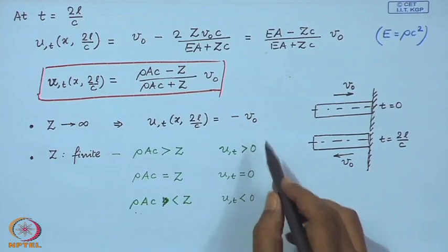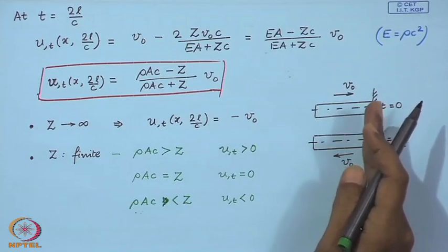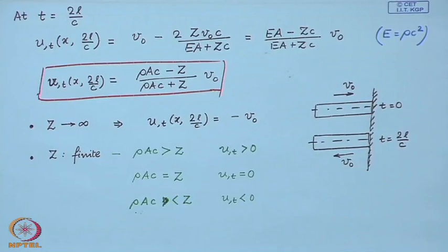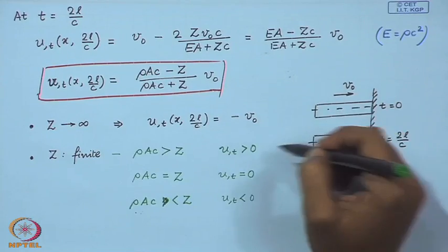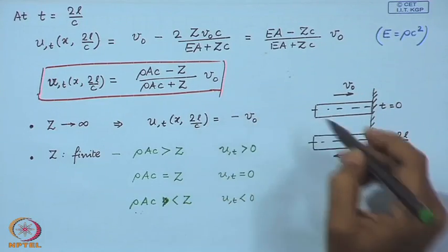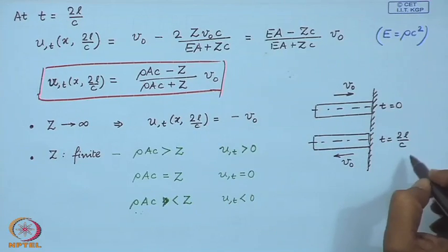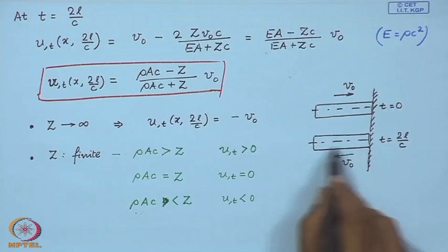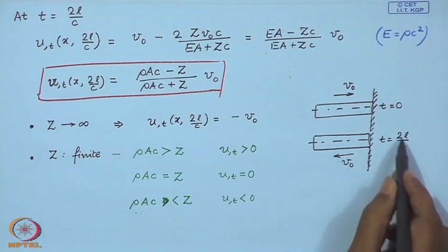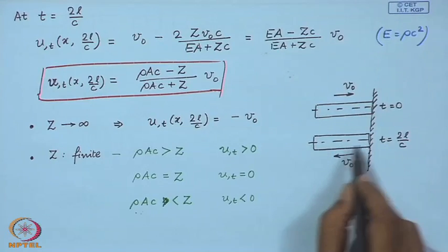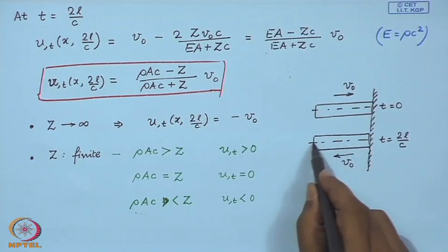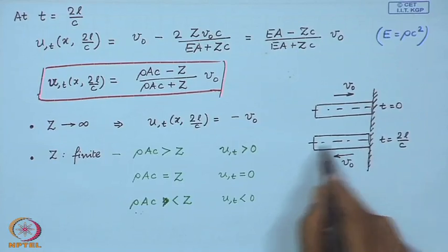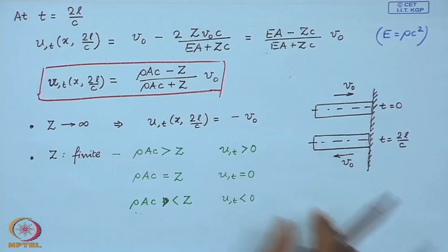So, here we also observe that collision, even though it seems instantaneous, it is not, as we can understand that this takes place after a time interval of 2L over c, where c is the speed of axial waves in this finite bar. So, the disturbance wave must travel this length of the bar twice before the rebound can take place, if at all there is a rebound.